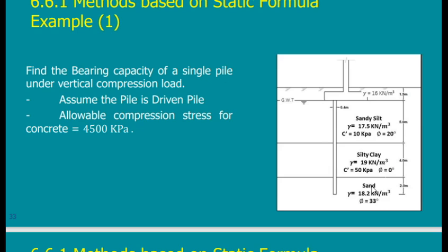First, we have to discuss which layer will carry end bearing and which layer will carry friction. Can anybody tell me? Bottom layer will carry end bearing. What about the friction? All of them. So the bottom layer will carry two things: end bearing and friction. Here, end bearing. This 2 meters will carry friction. And if I go up, these 4 meters will carry friction only. Then these 5 meters will carry friction. So I calculate each one alone.